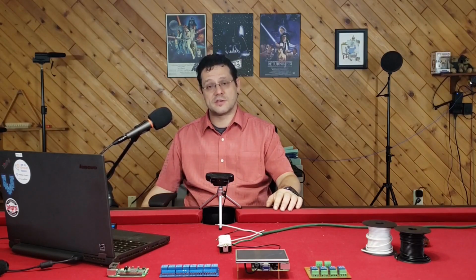Similarly, the various sensors Shelly makes report their readings this way, although there is some inconsistency in data formatting that I'll go over in the appropriate video. The relays will tell you if they are over temperature, and you can even lower the internal overcurrent protection. Other devices report battery status and other conditions you can make good use of to notify you when something needs attention. Installing and starting the MQTT server is probably the easiest thing we'll do in this entire video series.